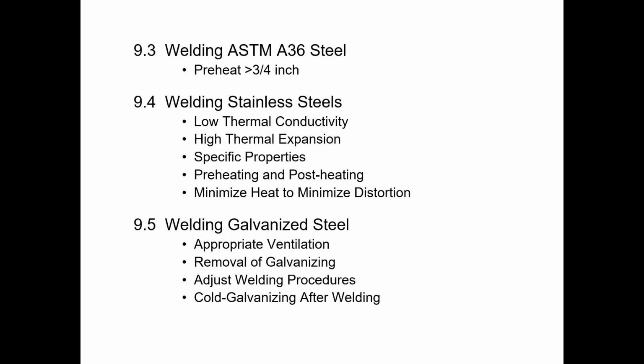It's probably better practice to grind off that galvanizing on the surface locally, because if you don't, the welding is just going to burn it off anyway. You're going to have to recoat it with cold galvanizing spray after the fact anyway. So it's better practice to grind that off, so that you don't risk breathing that in. And obviously, what we've just described represents an adjustment to the welding procedure.